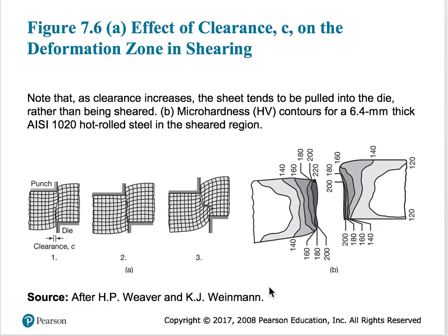Typically what happens is that you might have a rough fracture surface. If you would like to have a smooth surface that will nicely shear off and create a clean edge, it needs to be done at a very fast rate.